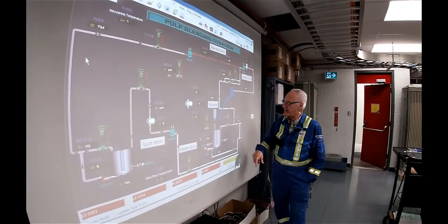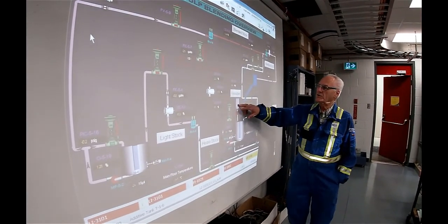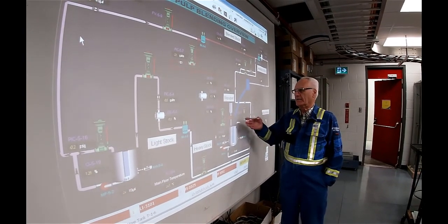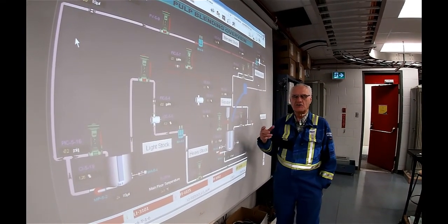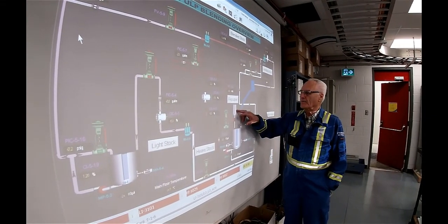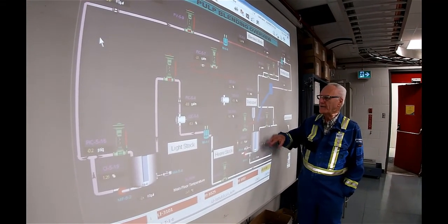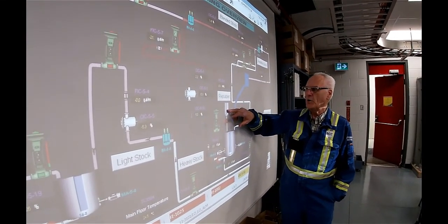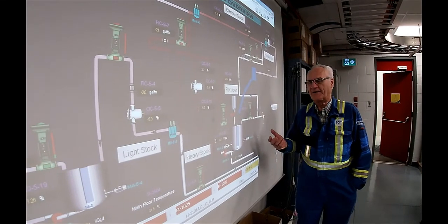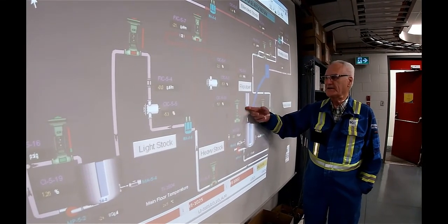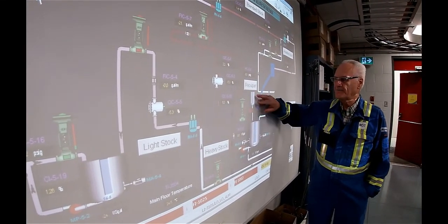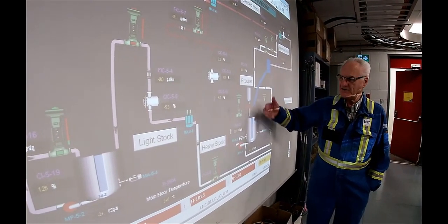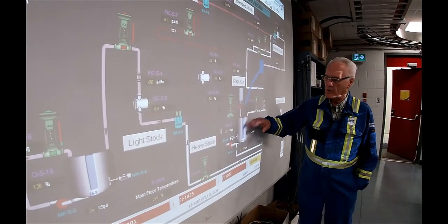So the process itself is we're going to go through this morning and make a batch of pulp in here, and we have a repulper where we're going to load in sheets of pulp stock, and it takes 80 sheets and about 170 gallons of water in here to make up around a 3.5 to 3 3/4% consistency pulp stock. Then we'll dump it into a heavy stock tank, and it takes 8 batches to load this whole system up.